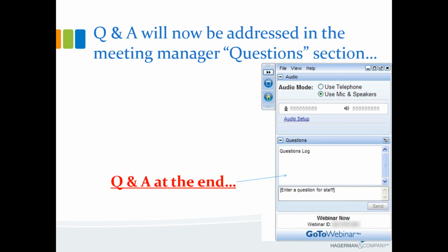Okay. Can the frame be imported into a Revit family for further modeling? I believe those imports going from Inventor to Revit would be what we would call dumb solids, are they not? They're going to go in there as dumb solids, but in Revit, it depends on how you get them out of Inventor. If you use BIM Exchange, you can export as an ADSK file, which is going to give you some mapping capabilities for connections and things like that. It's typically used for, like, if you make an HVAC unit and you need to map out hot water supply, cold water drainage, electrical in, things like that. That's going to give you an ADSK file.